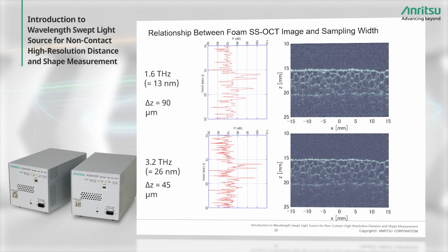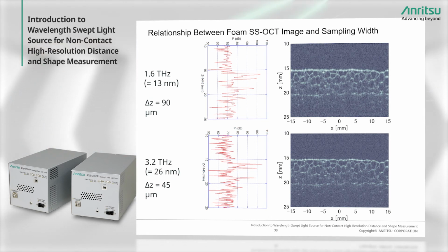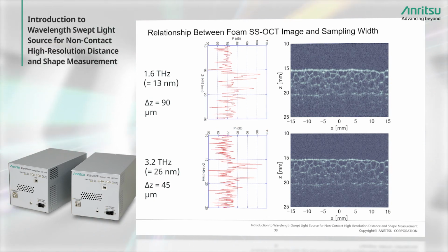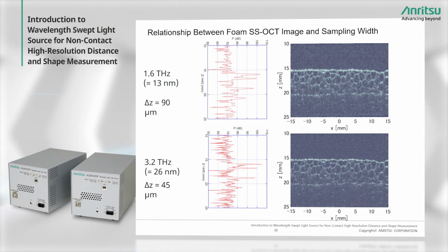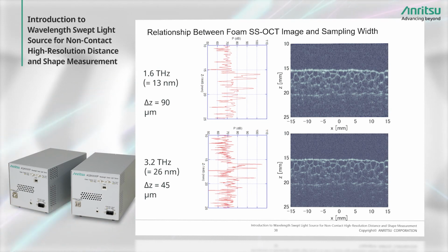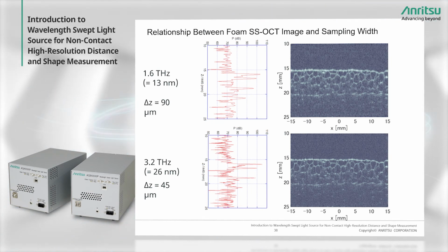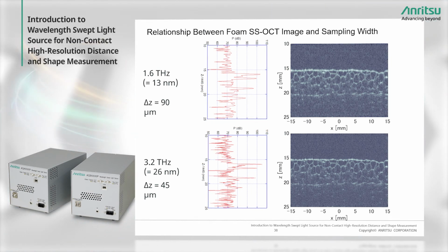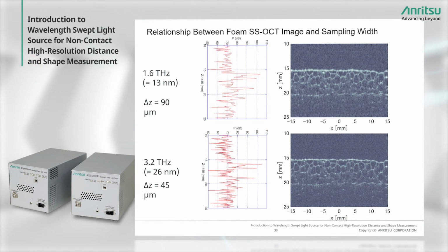This OFDR technology is exactly the same as SS-OCT. Put simply, although distance measurement only detects peak positions, OCT can measure the distribution of the reflections using the FFT spectrum. This shows a measurement example looking at the cross-section by scanning in the horizontal direction.